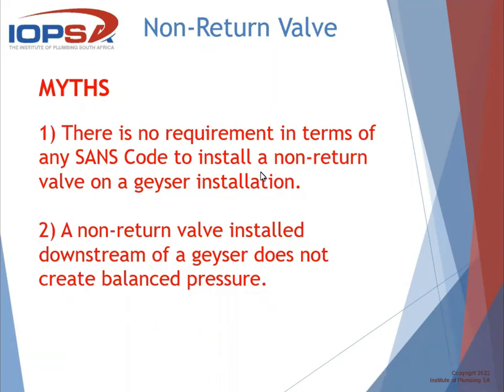In other words, you've got a hot water source quite far removed from the furthest draw off point, and so you've got a supply and a return line, linked to a pump, and that's okay. Now, I'm not going to go into how it should be designed, but the fact is that's a heat-eating monster, number one. So it's got to be properly lagged and properly designed and accessible.